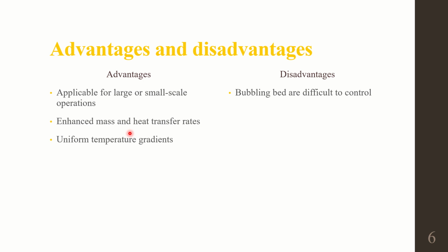There is one particular regime called the bubbling regime, in which we can observe bubble formation inside the fluidized bed. When dealing with bubbling fluidized beds, it becomes difficult to control the bubble formation. Understanding the complete dynamics of bubbling beds is essential to control the bubble formation inside them. So that is one disadvantage.